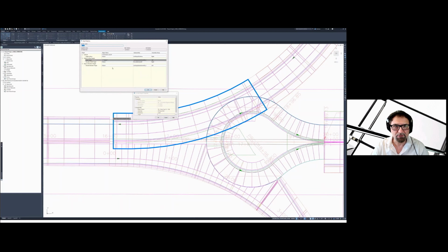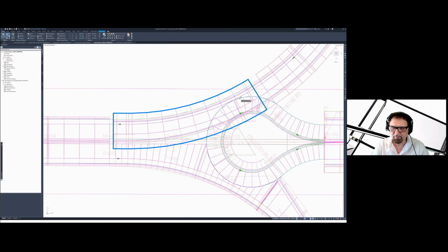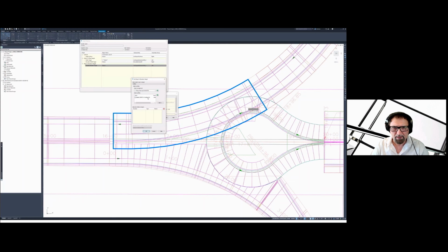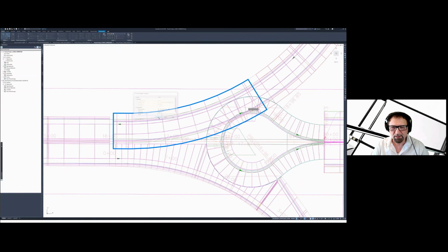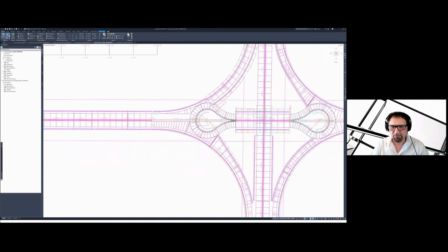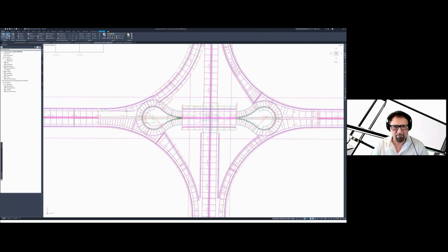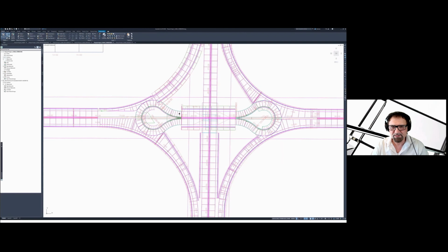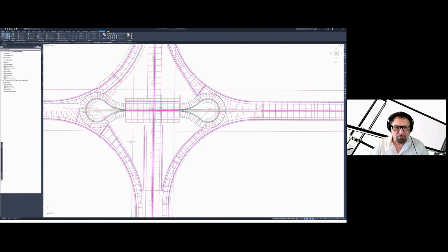And basically, I'm going to do the same thing for the elevation using the profile. Also going to use the profile on that offset alignment. And that's using that temporary surface. I'm just going to click that. So just this one to illustrate what we got. I think I have a part of the leg alignment missing there. So what happens is, I'll show you over here.